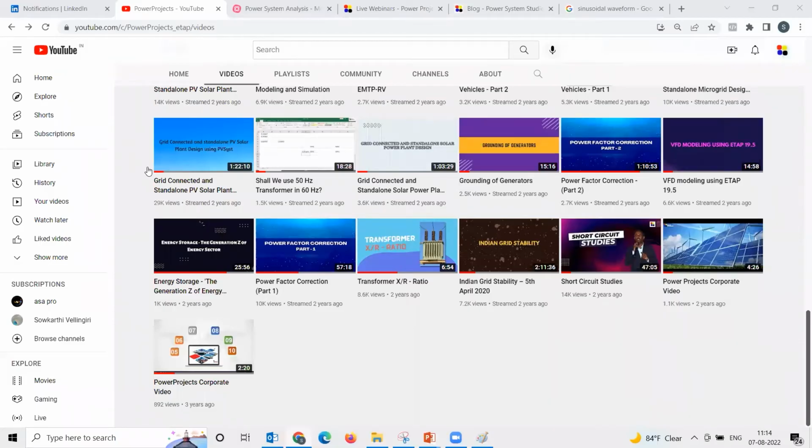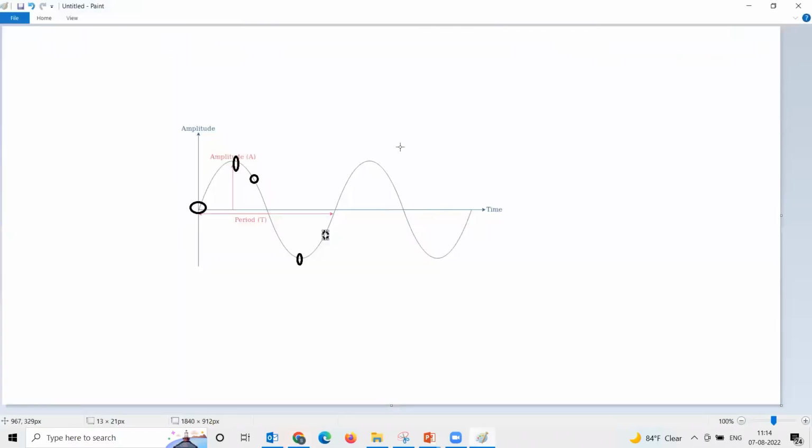which means my symmetrical current, okay. But if we talk about my asymmetrical current, my DC current, my peak value, all these things will change with respect to the change in the instant at which the fault has occurred. Now let's ask another question.